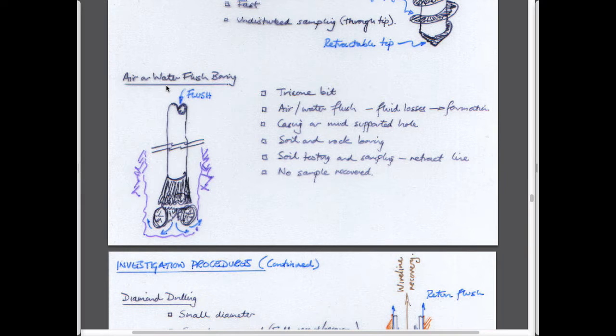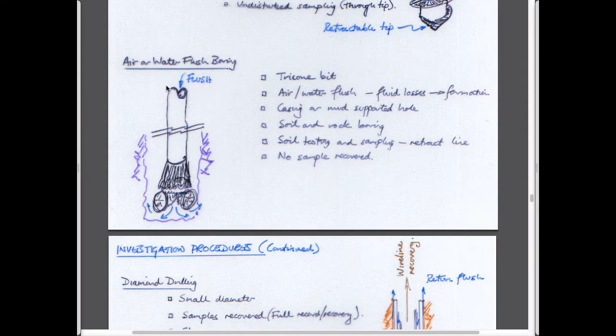The sonde might be a video camera that you pull along the core hole. It might be a gamma ray detector that tells you something about whether you have shales or clays there or not. It might be a neutron detector that tells you something about the moisture contents of the material. It might tell you what the seismic acoustic velocities are. All of these things you can rent very nicely from Schlumberger or Baker Hughes, and they'll charge you for the pleasure of doing that. It's not used so much in the water environment business, but it certainly is a standard way of logging holes in the oil patch. And so those are the three methods.